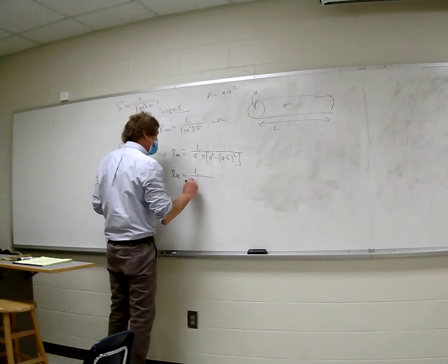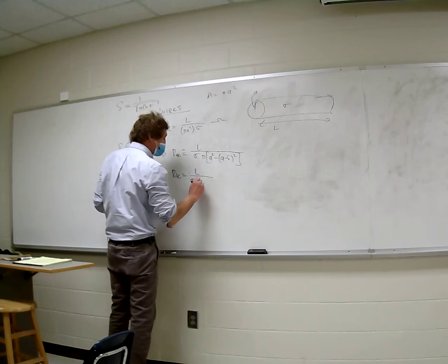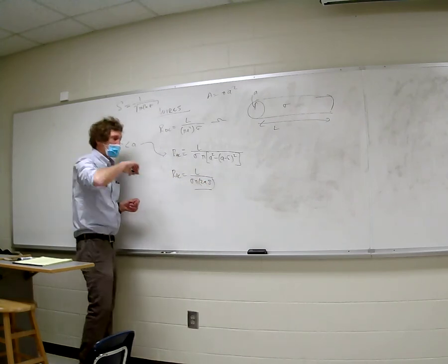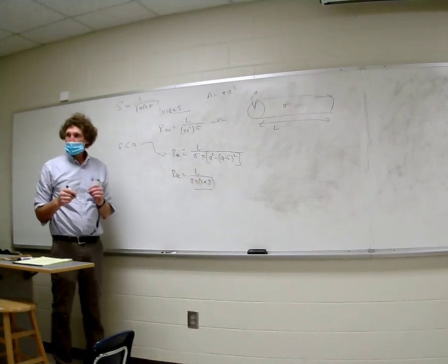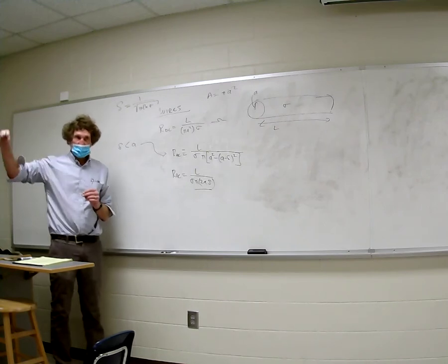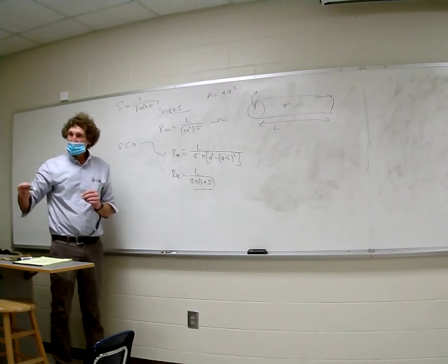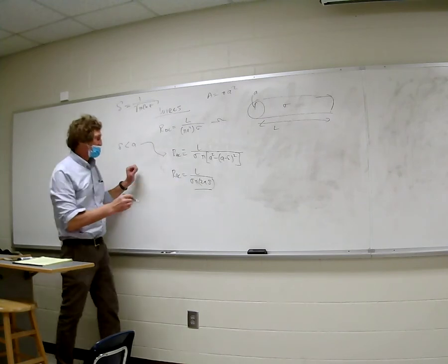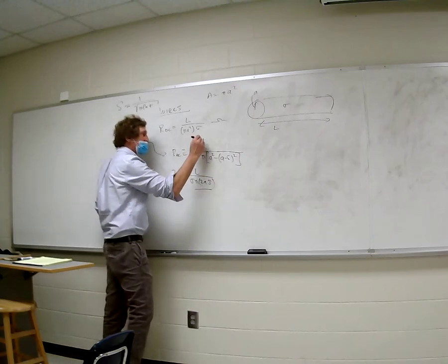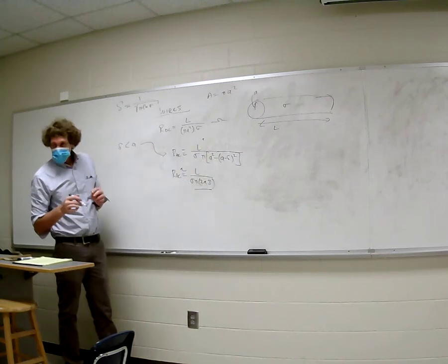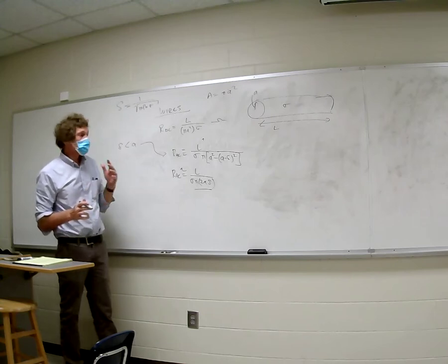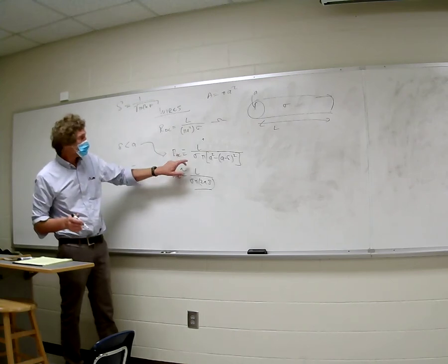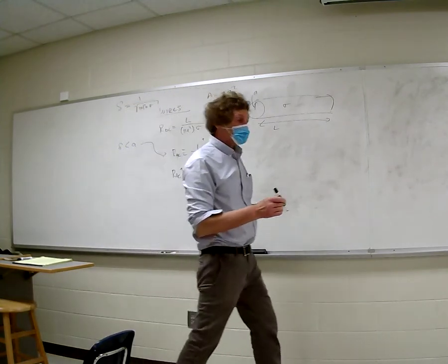And this usually approximates as L over sigma pi, and then there's going to be a factor of 2A times the skin depth here. What this really is, is the perimeter's length times the thickness of the skin depth. The perimeter would be 2 pi A of a wire. That's the outside length, and it would be times the skin depth thick. Y'all follow me? That's an approximation. This is exact, but generally speaking, you usually have skin depth either much less or much greater. You don't have that gray area where you have to default to that. All right, that's for the resistance of wires.